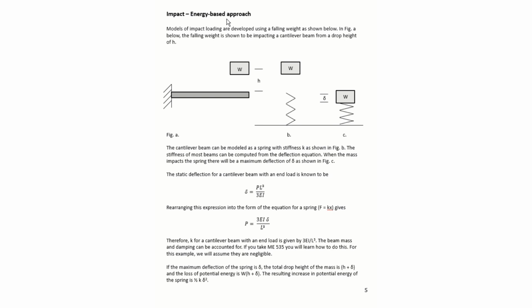The idea behind this is based on conservation of energy. For example, if we have a weight W that is above a cantilever beam by a distance h, we can model this cantilever beam as a spring. And we can actually compute the stiffness of this cantilever beam spring. You can do that by knowing the static deflection.